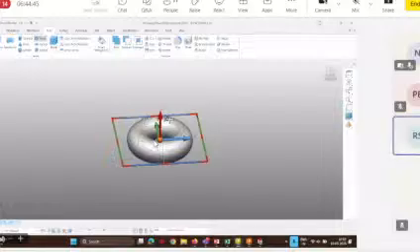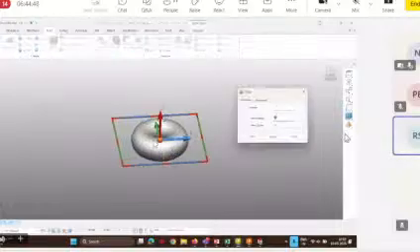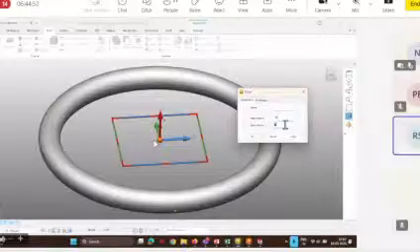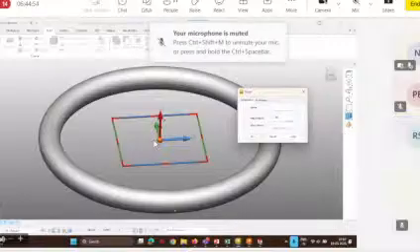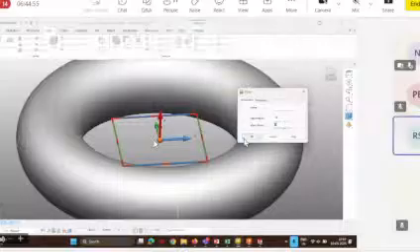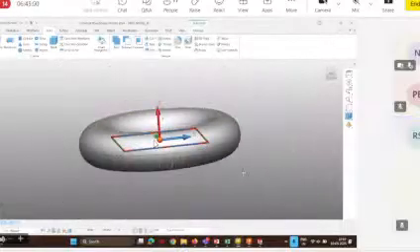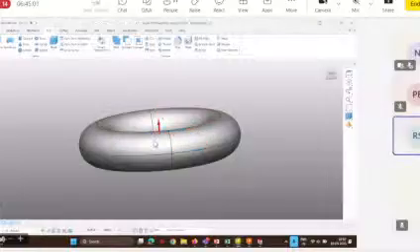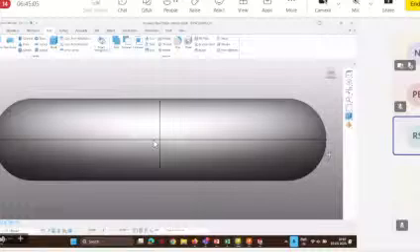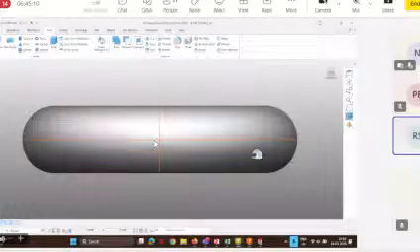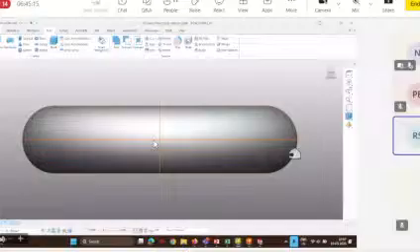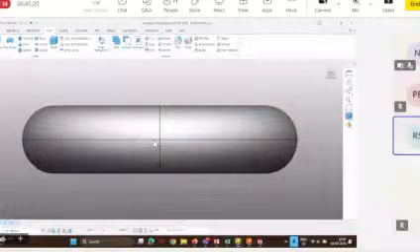Let's define the diameter to be 100 and 30. All right, so suppose I want to deposit this part. If you observe, this is nothing but an overhang. So how to encounter this? One way is I have to tilt either the bed or the deposition in such a way that gravity comes in this direction, in this tangent direction.